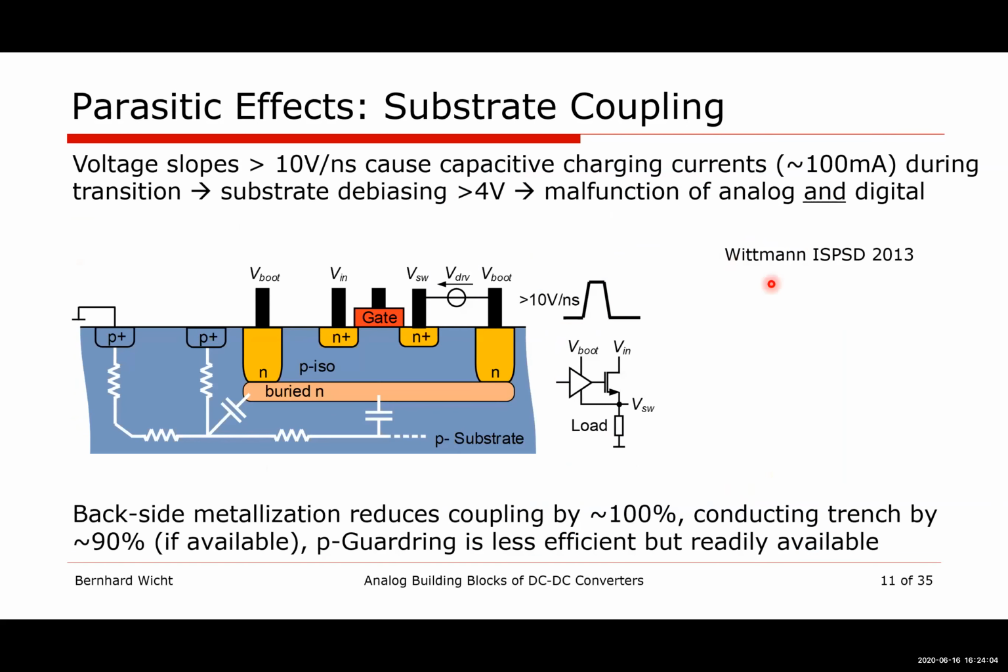Actually, yes, both, sure, on parasitics and mostly on substrate coupling, I actually have two questions. One is if you have any estimation for the distance between switching regulator and other circuitry where the substrate coupling effect decreases to, let's say, an acceptable, reasonable value.